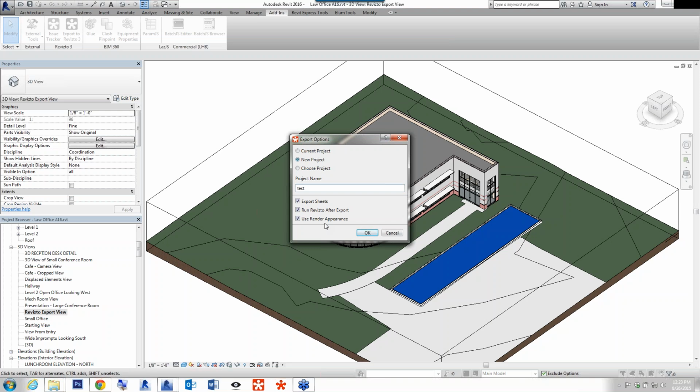If you're exporting a really large model, like right now we're working on a 1.4 million square foot existing model, creating an as-built for a client, I've unchecked this so that I can export the entire model with MEP and lots of piping and things like that in there, and more smoothly navigate the project.